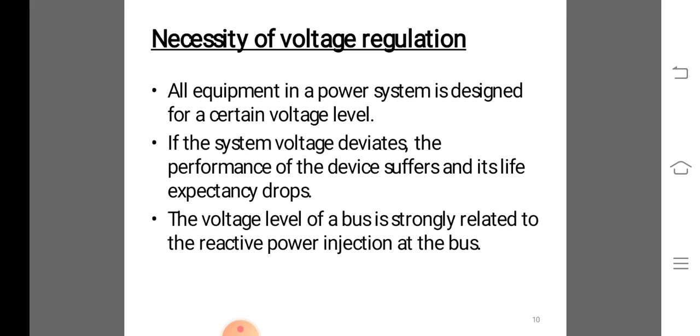Suppose the static accuracy limit is denoted by AC in percentage with reference to the nominal value. The error voltage is to be less than AC/100 times ΔVref. The larger the overall gain, the forward block gain K, the smaller is the steady state error, but too large a gain K